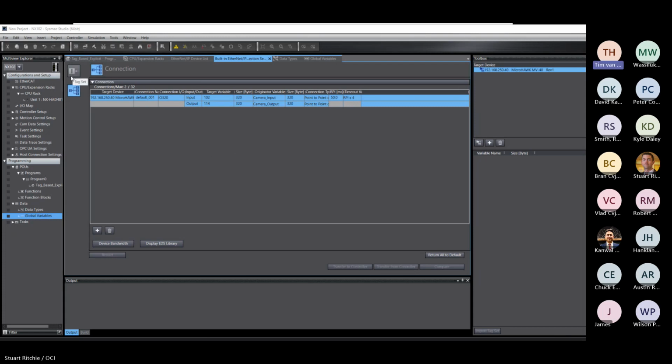As an example, I had an Ethernet IP connection with 128 bytes, and I made a structure of it to make it easier, like you did with this camera. The structure came back as 132 bytes, and it gave me a mismatch, even though if you add them up manually, it comes to 128 bytes.